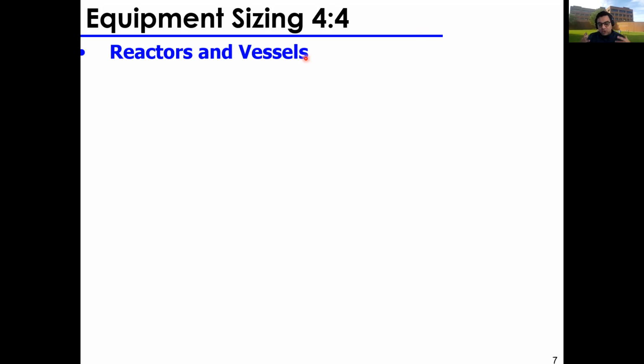Process design, as a process engineer, you do this. Reactor design will be maybe a separate engineer who will focus only on designing the reactor, looking at the details, at the controls, how fast we are running our mixer, what type of mixer we are using, whether we have to have some internals to divide this reactor into chambers, compartmentalize this reactor. If you have a PFR, how are we cooling this unit? Do we have one tube or a bunch of tubes in a cooling liquid? All of these details really come into play later on.